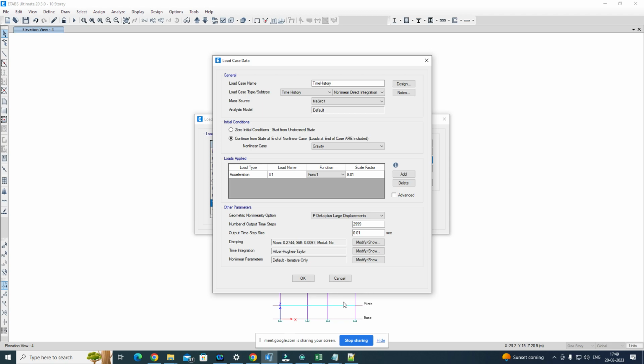For example, you want to construct a building at some site in Roorkee. Now if you really want to do some ground motion analysis, you have to select the ground motion which is reflecting the site characteristics of Roorkee. But there is a higher possibility that you will not get ground motions which exactly match the characteristics of that site. So we have to go for ground motions from some other site which is not matching exactly to this site.